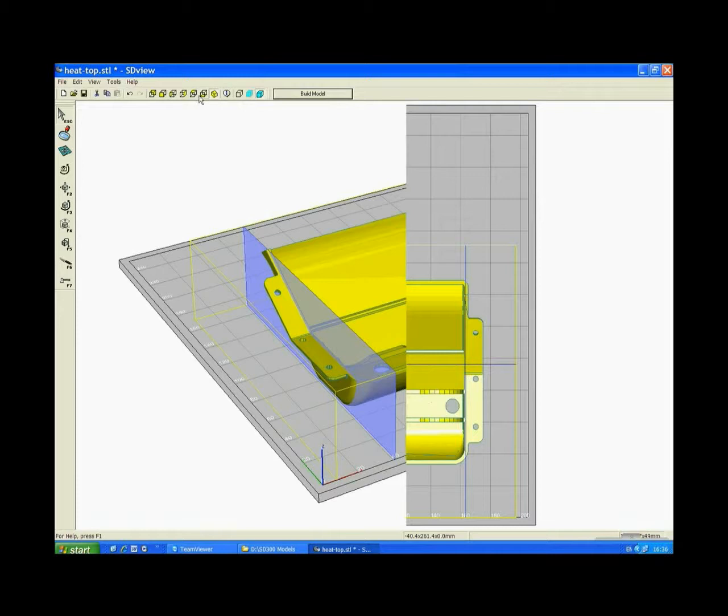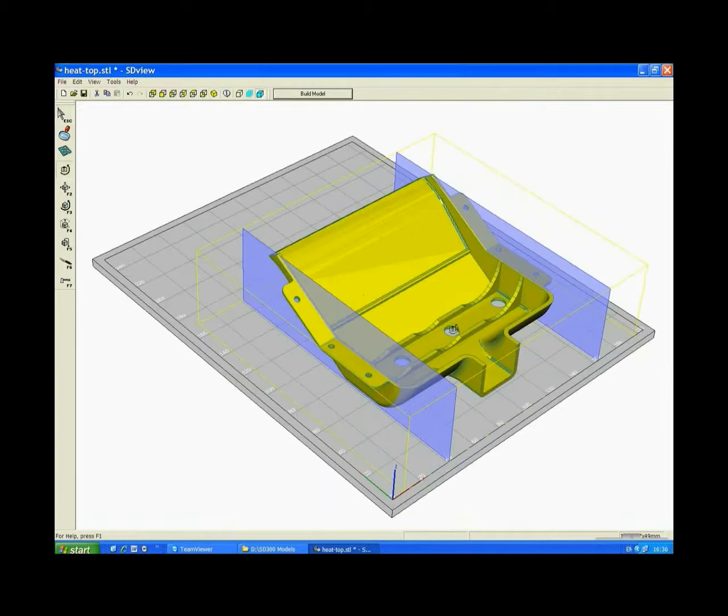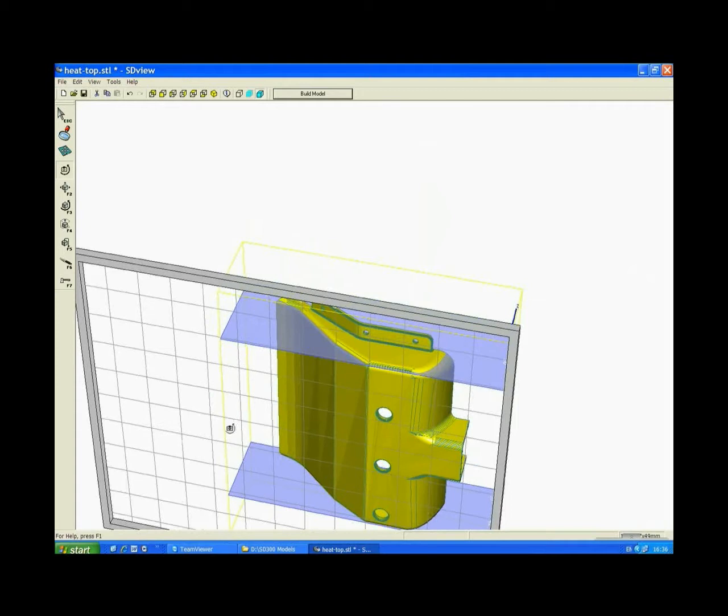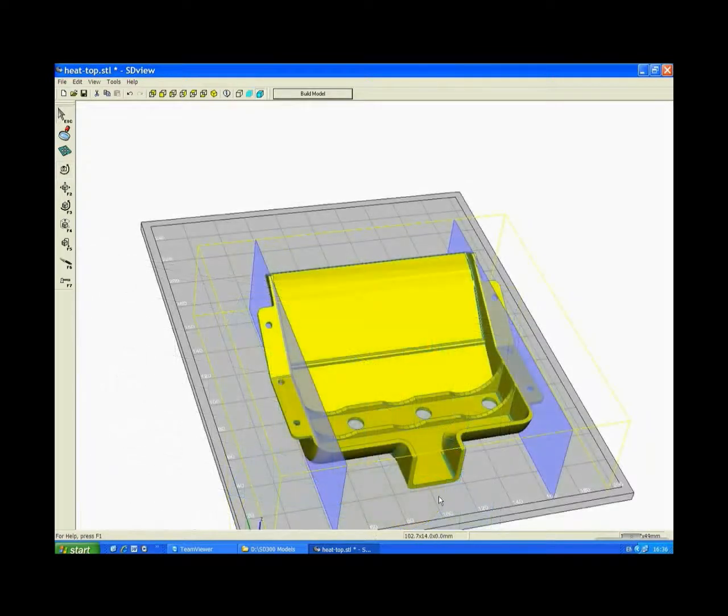As you can see, now the part can be easily peeled from both sides, top and bottom. Support material in this area will never go around the part into this area. Finally, we will close the last small opening in the X and Y axes so support material coming from around the part will not enter the part itself.